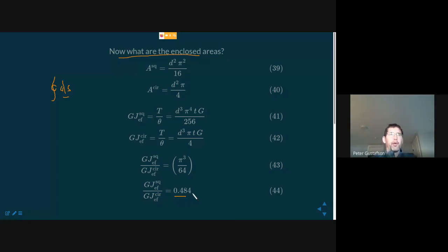I would say that if you're starting to exceed 20 to 1 on the radius to the thickness, you've gotten really thin. Probably too thin. 10 to 1 is probably in the right neighborhood. You can maybe get away with a little bit less. That's to avoid buckling, but there are a number of other factors that come into play, obviously.